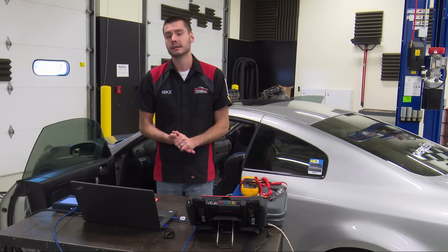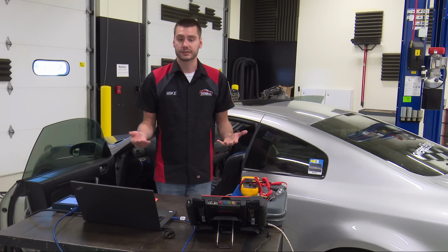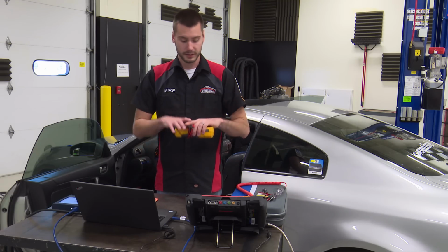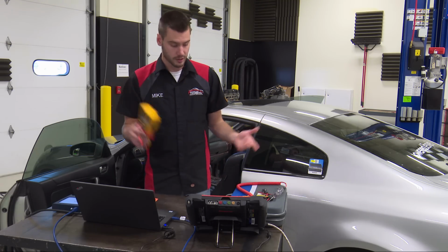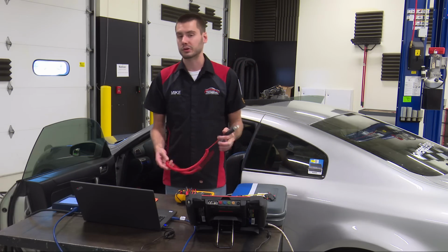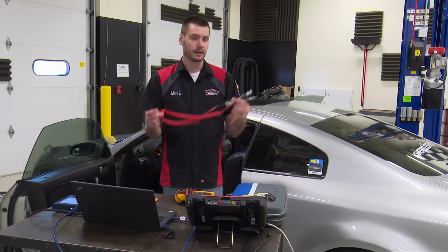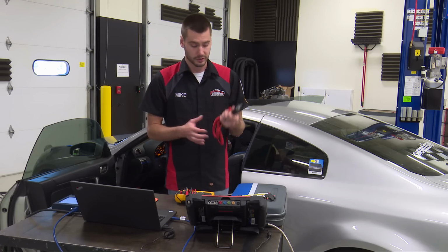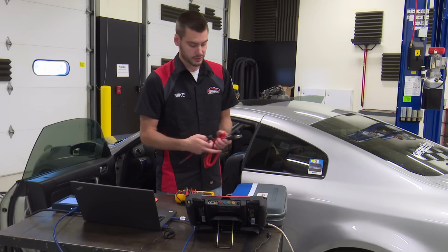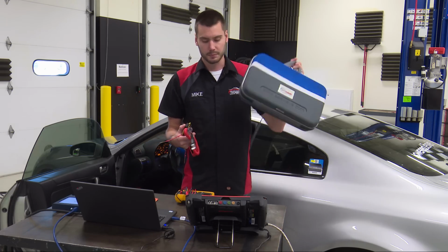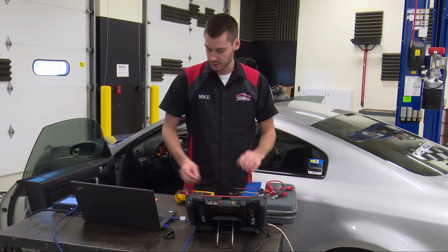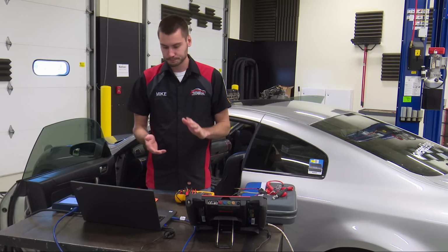So what do we need to figure all this out? Well, there's a couple tools that are going to be really handy. A voltmeter of some kind, so you can check for powers and grounds. A test light, so we can put a small load on the circuit. Now, a window motor is probably going to pull a lot more than this test light, but we can put a small load on the circuit. I got a couple of fused jumper wires, and then the pinout kit, so we can pin out our connector without damaging our terminals.